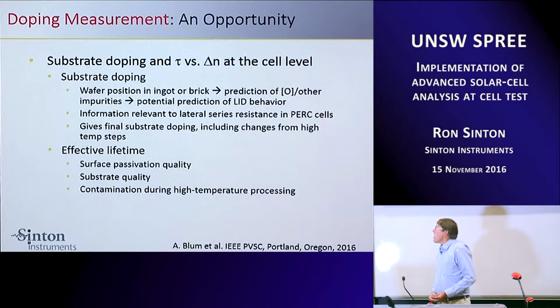And this can give you a proxy for the oxygen level because you know that there's more oxygen in the seed high resistivity side of the ingot. It could give you a prediction of the LID behavior. It also gives you information relevant to lateral series resistance in the case of PERC cells.